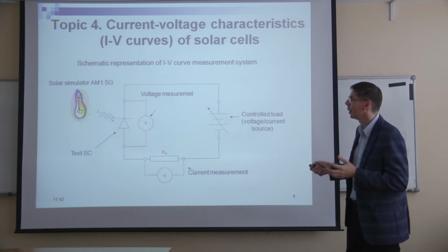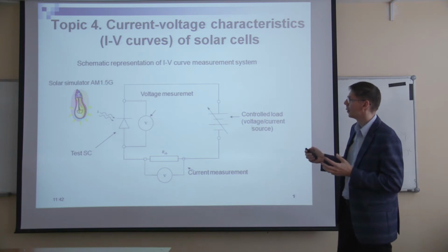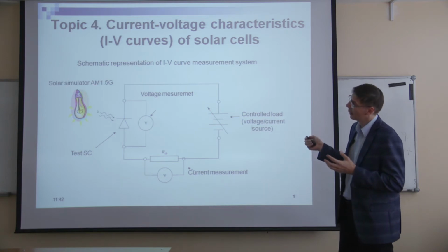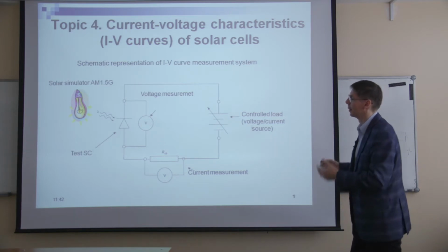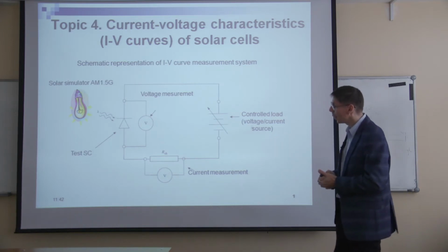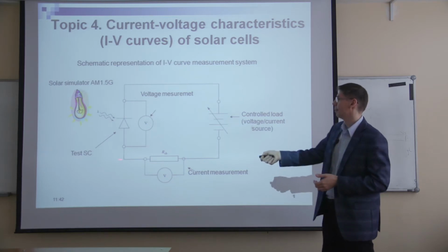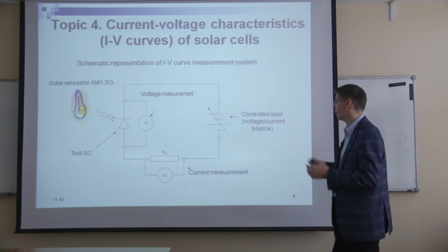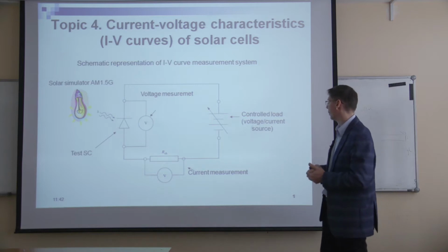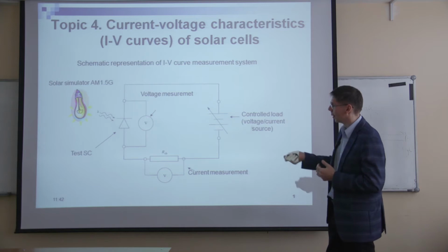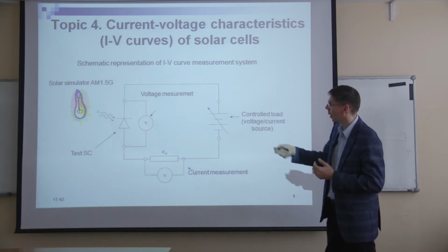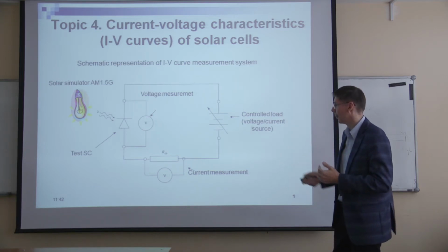It's like a diode here in this equivalent circuit. Then we can think to measure the voltage which is dropped on this solar cell, and using some standard power source, we can apply some voltage and measure the current.